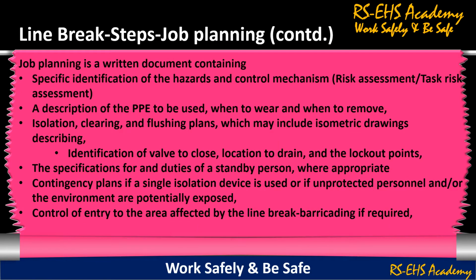Line break step: job planning. Job planning is a written document containing specific identification of the hazards and control mechanism, that is risk assessment or task risk assessment, a description of the PPE to be used, when to wear and when to remove, isolation, clearing and flushing plans which may include isometric drawings describing identification of valve to close, location to drain and the lockout